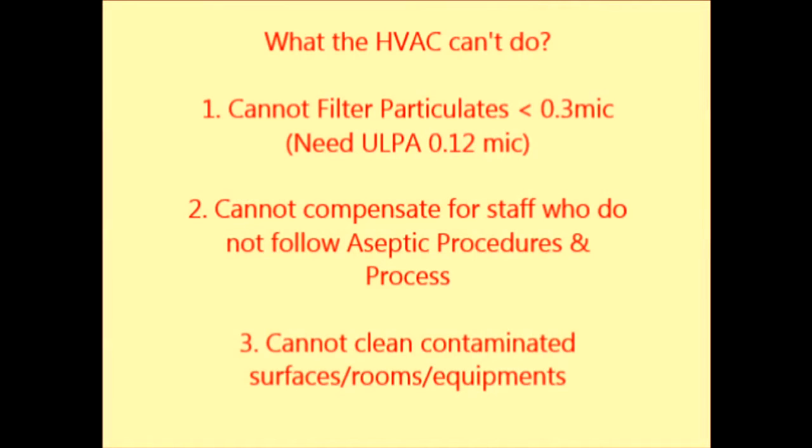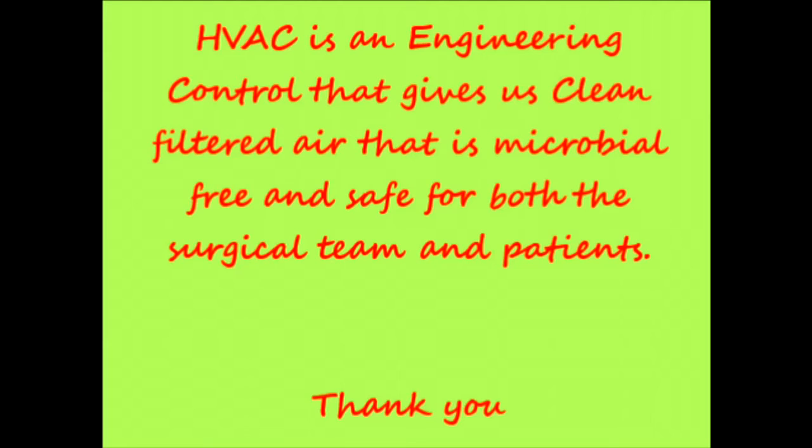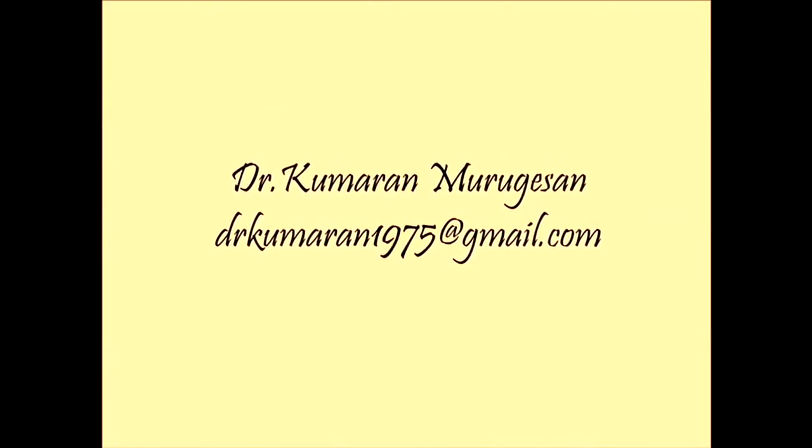We should also know what the HVAC can't do. It cannot filter particles less than 0.3 microns, and it does not compensate for proper cleaning, as shown by a previous speaker. So the HVAC is an engineering control which gives clean filtered air, and it is safe not only for the patient but also for the other surgical team.